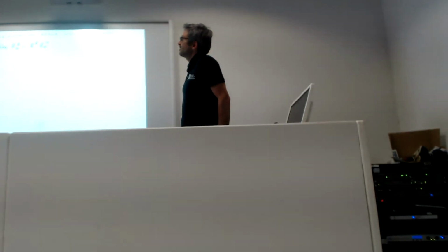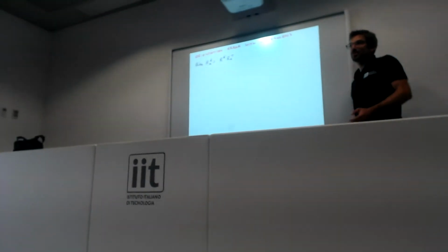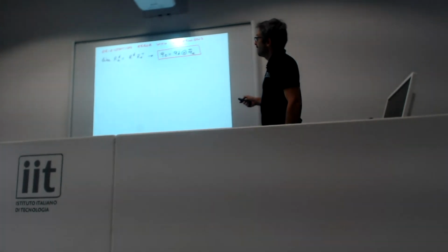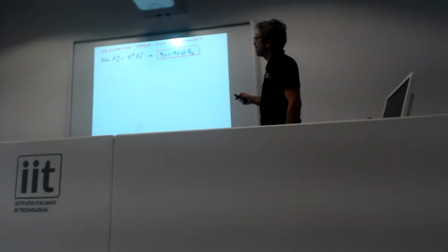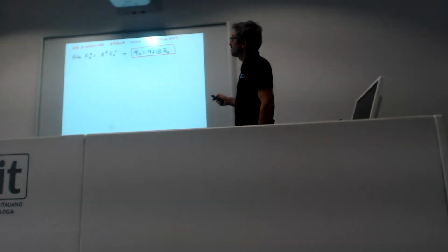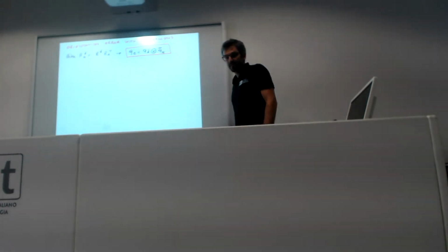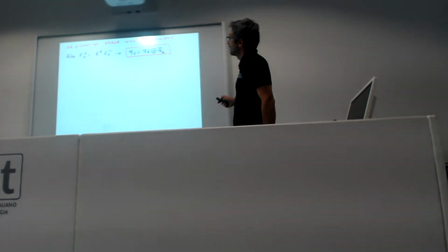To compute the rotation error, we do something similar to the rotation matrix, and we find that the error quaternion is equal to the desired orientation quaternion multiplied by the inverse of the actual orientation at the end effector, because the transpose is like doing the inverse.